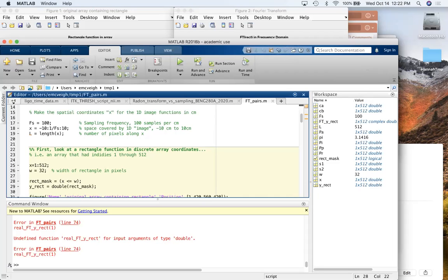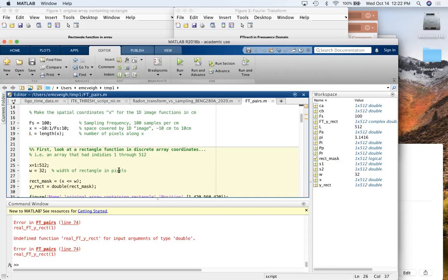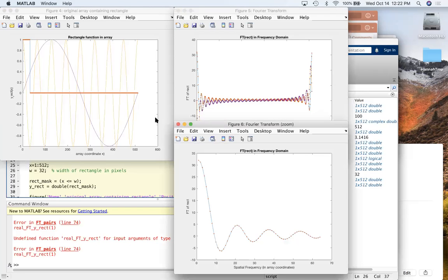Can the low pass filter be applied in frequency? Oh no, okay, I did that one. How come the waveform repeats? That's a very good question. I think I answered it, which is, when we look at our output here, let's just run it again. And yes, the function goes down as 1 over x as we're moving out here, and then it comes back up. This is, in fact, that replicant that we were seeing due to undersampling, right?